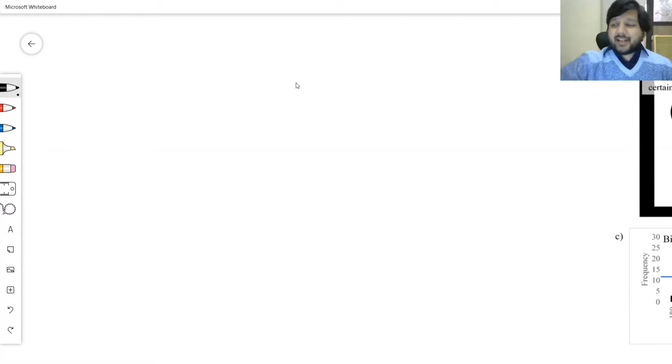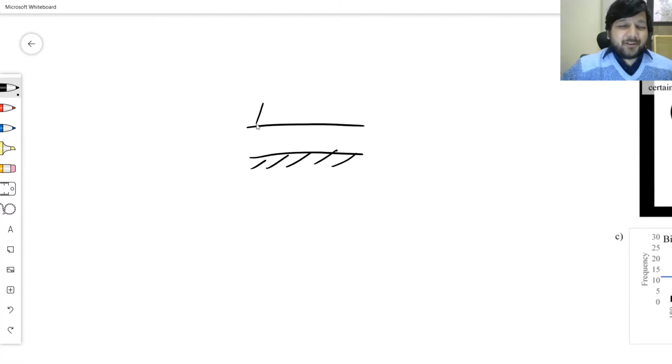Okay, so we started off with an algorithm called artificial potential field. It's a reactive algorithm that looks at everything around and does lead the robot to the goal. But imagine a general scenario where I've got a pretty narrow corridor, and with a potential field, minus oscillation, traveling inside the corridor is okay, that's possible.